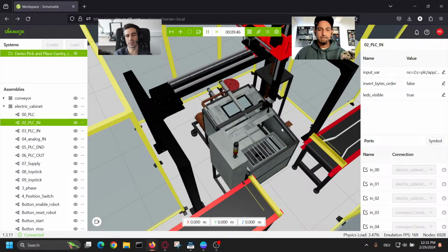More than latency, the issue with OPC UA is that if you just write the name of the variable, the client needs to crawl the entire server until it finds it. So it's just in the beginning. It may take a lot of time to find the variable. Once the variable is found, the latency is going to be the same.